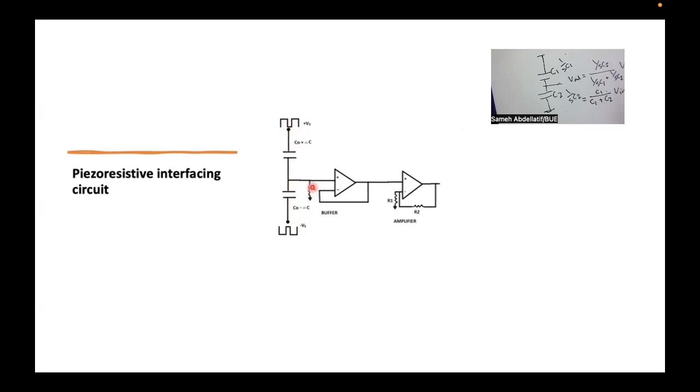So you can tune the discharging time by simply tuning the RC value. All of you know that this RC value is the factor determining the discharging time for any discharging capacitor. So this is a very important piece of information. As I just mentioned, the role of this resistance is to guarantee a discharging path for those capacitors. And you can easily control the level of discharging, or what we can call the level of fluctuation in your voltage here, through controlling the value of R and C together to control the discharging length.